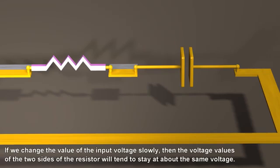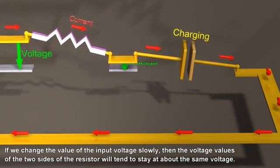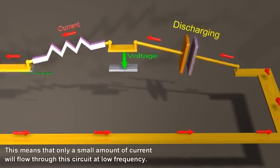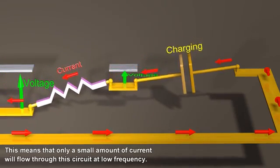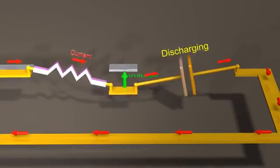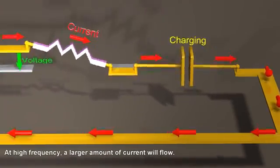If we change the value of the input voltage slowly, then the voltage values of the two sides of the resistor will tend to stay at about the same voltage. This means that only a small amount of current will flow through this circuit at low frequency. At high frequency, a larger amount of current will flow.